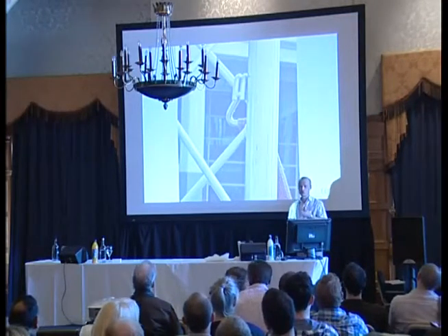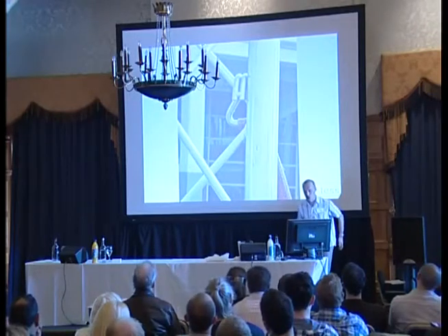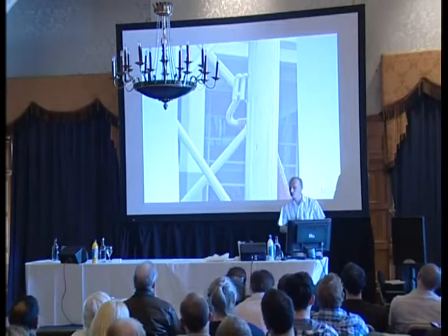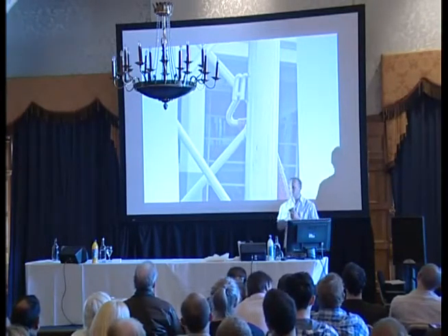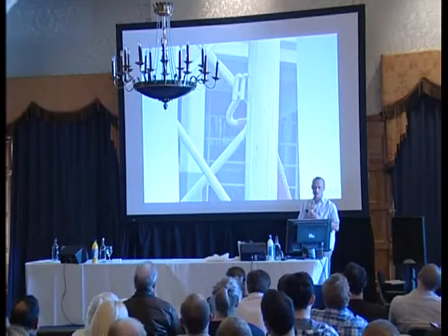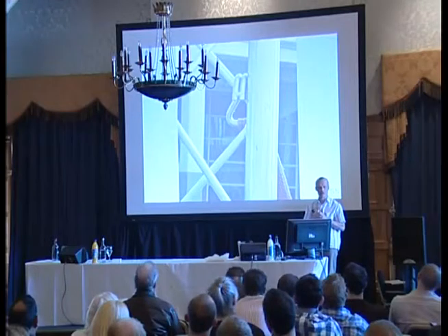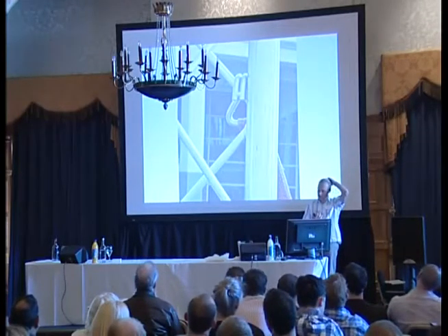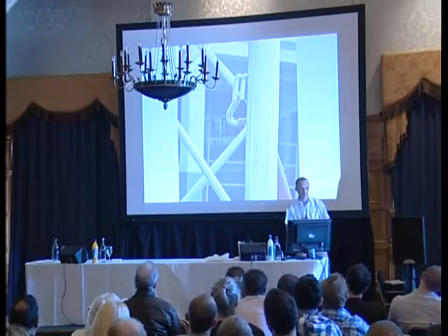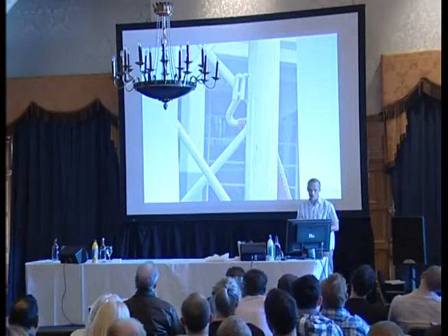Now, what's the water ballast there to do? Stop uplift, yeah? Now, is that diagonal on that very small piece of truss designed to take upload? I'm not an engineer, but I would suggest no. With a nice, neat steel hook and a 5-ton ratchet strap over there, the first thing that's going to go is you're going to tear that strut out of that aluminium piece of truss if you get a big uplift. The 1-ton ballast will stay on the floor, the ratchet strap will be fine, but the truss will be lifted anyway, and then you're back to the same problem. You've got a roof that is unstable.